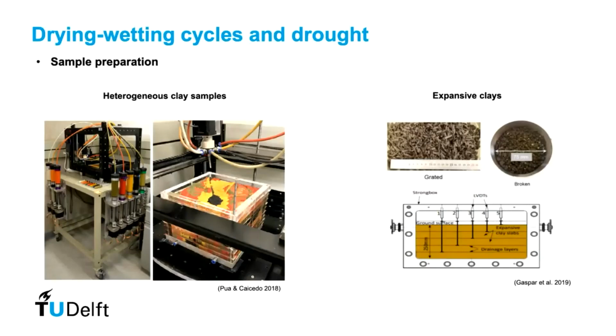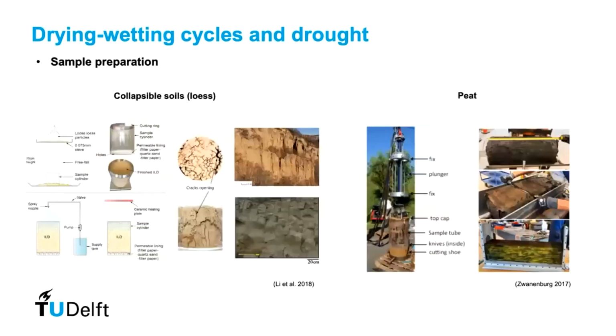That random orientation of voids certainly makes a difference in the way the soil interacts with a given structure and can tell us with more detail what we are probably missing by doing very uniform soil samples. Other aspects that can be explored are, for example, collapsible soils or peat, where it is not a sand or clay, the most typical materials we test in the centrifuge, but it has an internal structure that can certainly vary what we expect in the behavior.